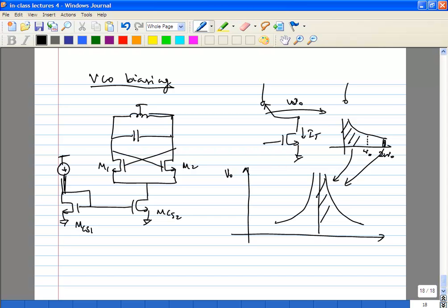That analysis, people have done it. I can show you the information, but there's just one thing to remember. Even if part of it goes into amplitude noise, because you have the varactors which are tuning, if you have any amplitude noise at this point, the varactor is going to convert it to phase noise, because the varactor capacitance varies as a function of the DC voltage. It will respond to any low frequency variations, so it will end up causing PM noise. We are going to look at that a little bit later in class.